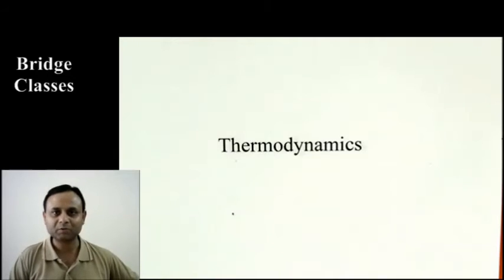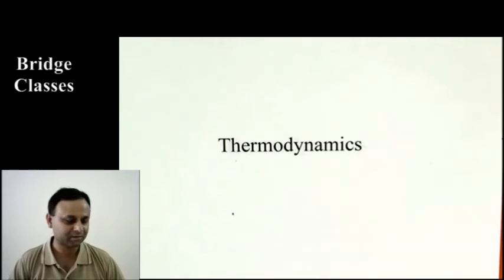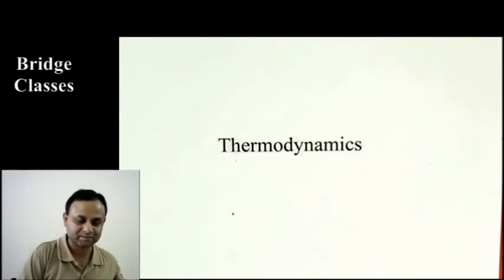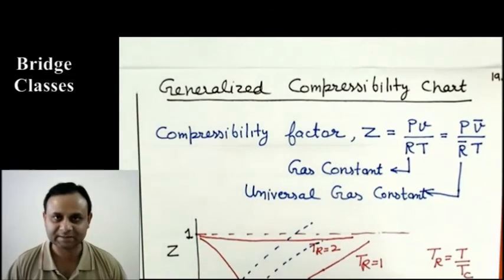So we are talking about these special cases now which simplify our life very much. In general you have to read all these values from tables, but if we treat the substance as incompressible, you see the life becomes very easy. Delta U is C delta T and delta H is delta U plus V delta P. So these are simplifications.